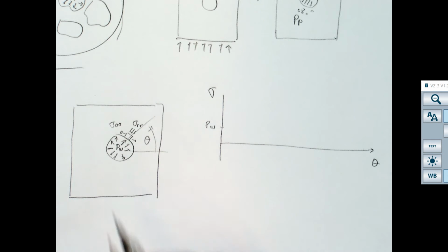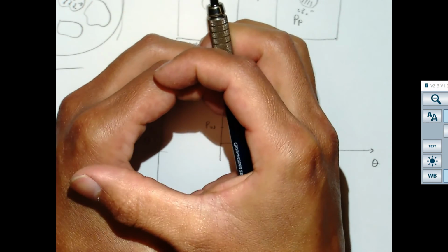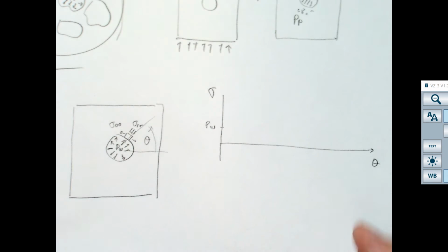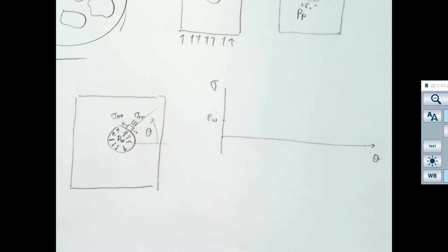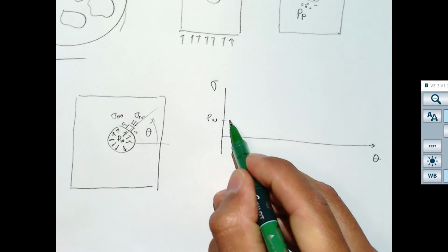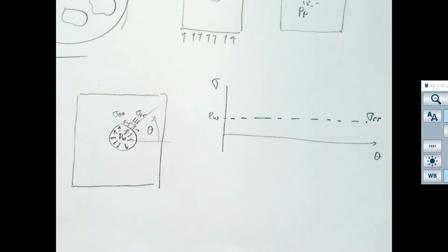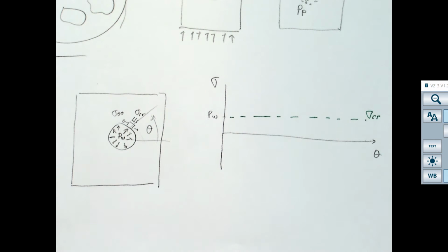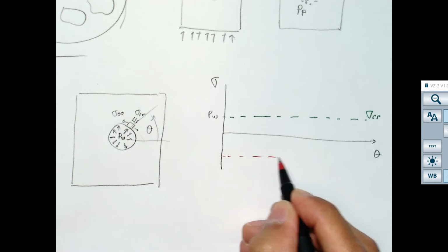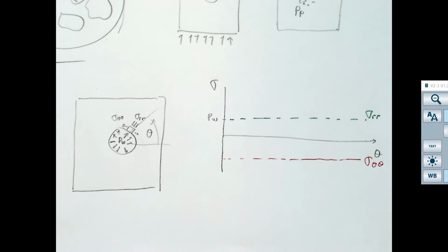If it had a size like this, once you apply pressure, it's going to get a little bit larger, and so it's going to be stretched in this other direction. So while the radial stress is going to be a compression, is going to be positive, applying a pressure is going to result in tension in the wall of the wellbore.